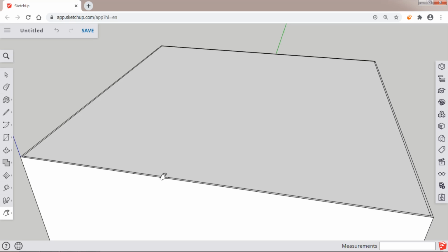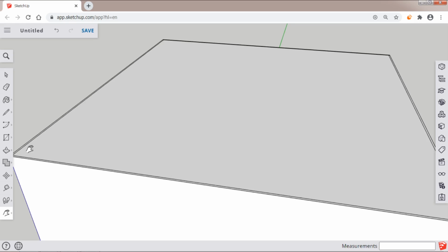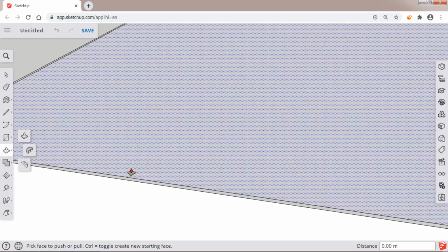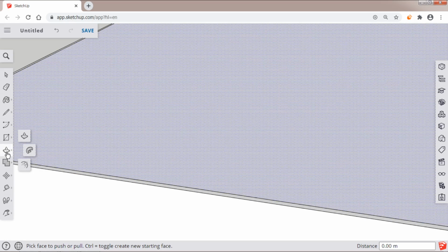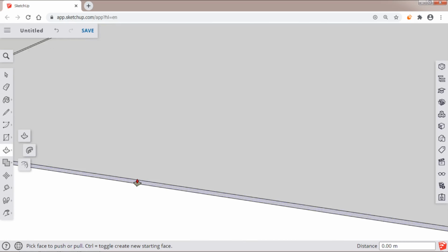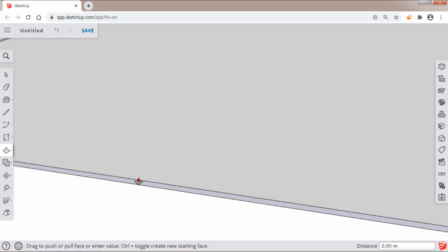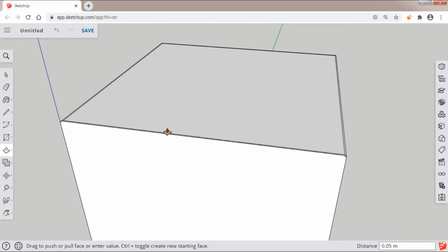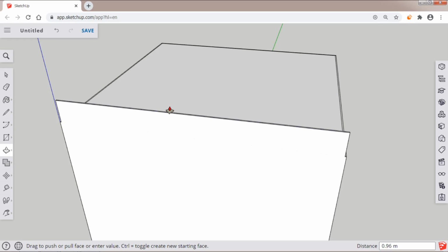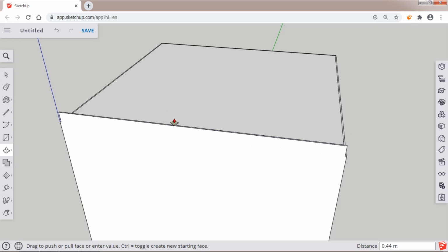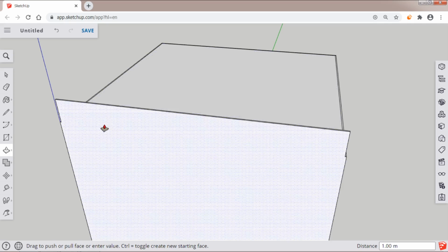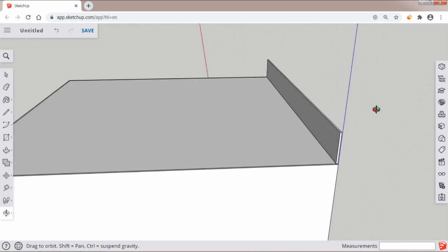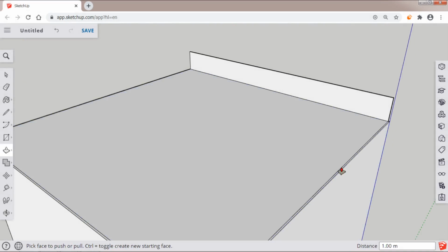Once we have drawn the basic rectangle for the parapet wall, again we will use the pull and push command to create a 3D parapet wall. So like this we are using the pull and push button. Again we will select the small rectangle that we have drawn on the individual side. The pulling height that we are clicking here, up to this we can pull, so the pulling has unlimited height. So we need to fix the dimension as 1 meter. We just write distance is 1 meter and again enter. When we click on enter, it creates a parapet wall of height 1 meter.